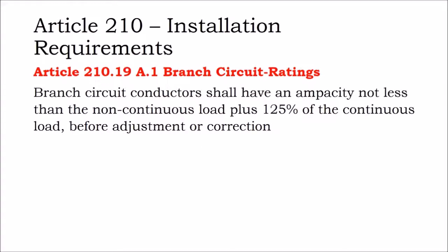And so on continuous loads that are under regular continued use, you will apply safety factors because those cables are under continuous current. You know, they're always on, they always have some heat in them.